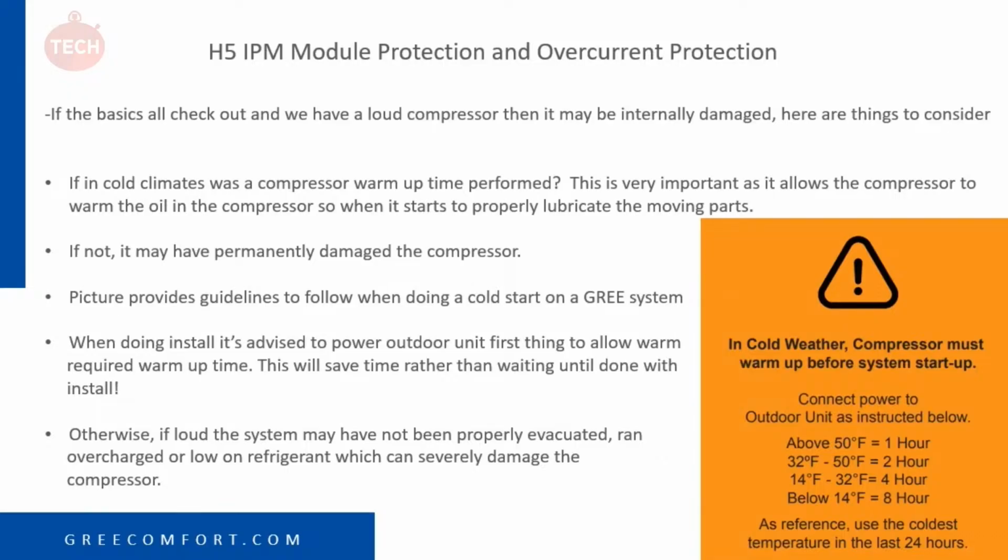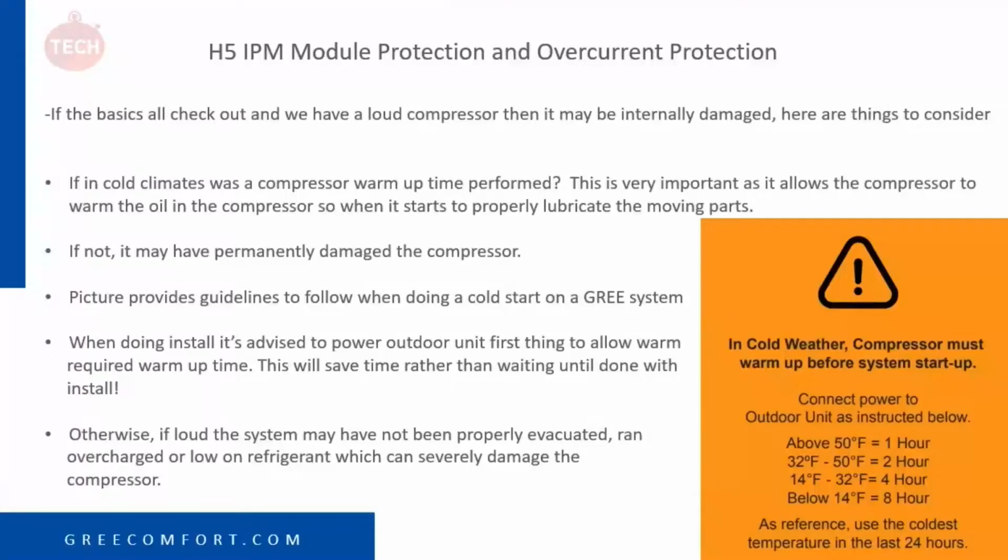We're going by the coldest temperature in the last 24 hours, so that's something to consider. If the coldest temperature in the last 24 hours is 50 degrees or above, we need 1 hour of compressor warm-up. 32 to 50 degrees, we'd want a 2-hour warm-up. 14 to 32, we want a 4-hour warm-up. And below 14 degrees, we want an 8-hour warm-up.